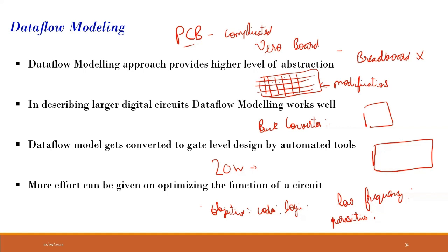Yeah, the buck converter, as you said, in Vero board we can purchase components and make it. Temporarily we can make it, but for that we need only through hole components. In Vero board we can use only through hole. Yes, correct. But there are some part numbers in the PCB where they are using SMD devices also.